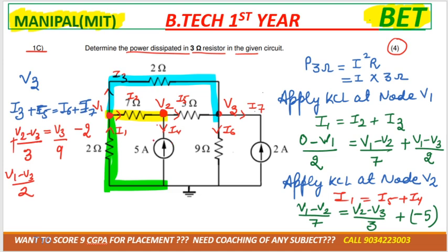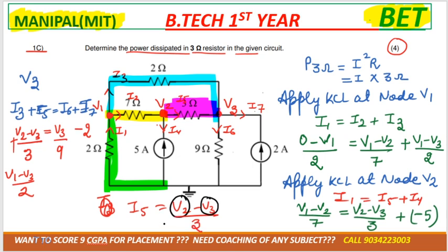So after solving these three equations, we'll get the values of V1, V2, V3. After getting V1, V2, V3, we can get the current across the 3 ohm. That is I5, right? The current across the 3 ohm is how much? We took I5, and I5 is moving, so it is V2 minus V3 divided by 3. We know the value of V2, we know the value of V3, so we can get I5 easily, and after getting the current we can substitute it over here, then we'll get the power. So this question is also easy.